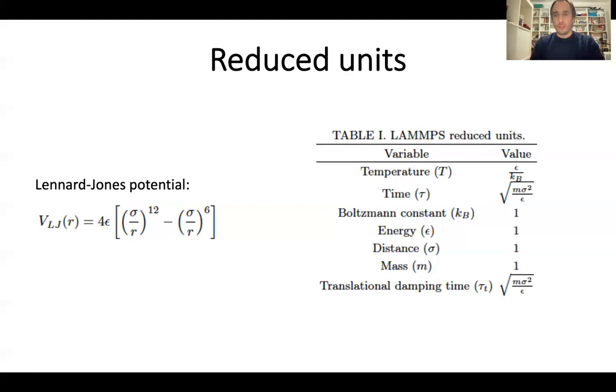The same goes if you choose the size of your particles: you choose a radius of 5 or a radius of 10, and use that as a reference. This is important not because you're using the Lennard-Jones potential, but because it will be a reference between all the values. So if you use 10 sigma as a radius, you can relate that to the real value. I try to explain this with some examples in my notes.